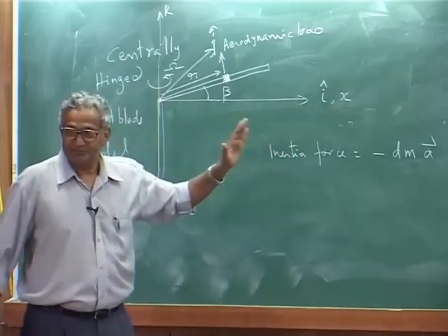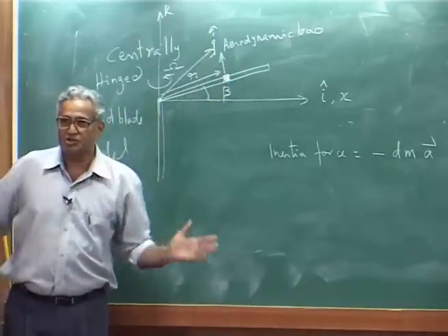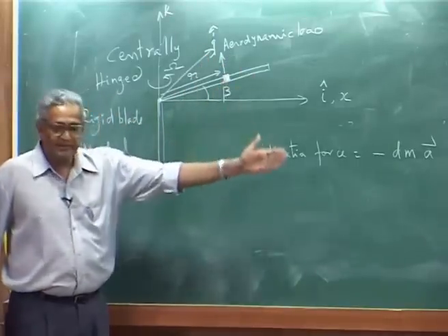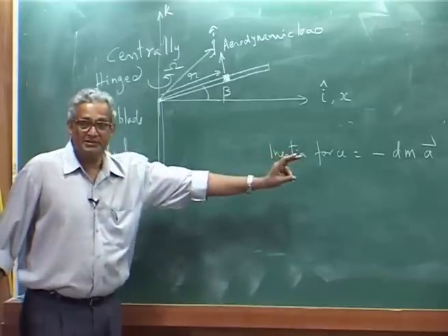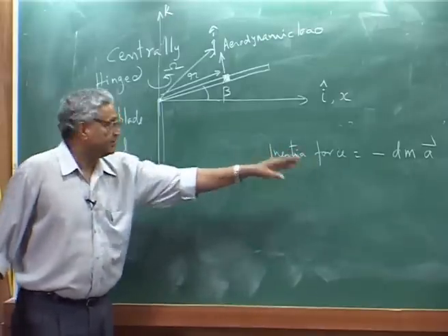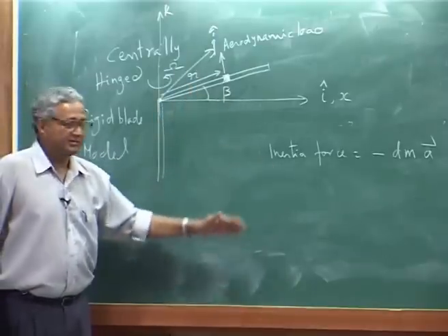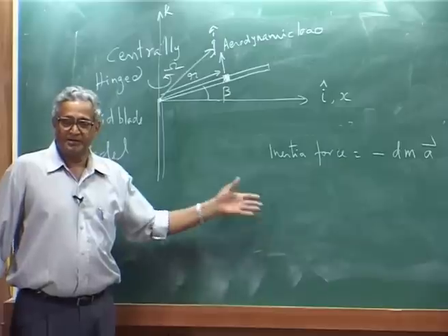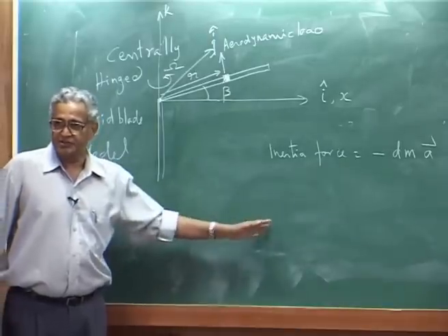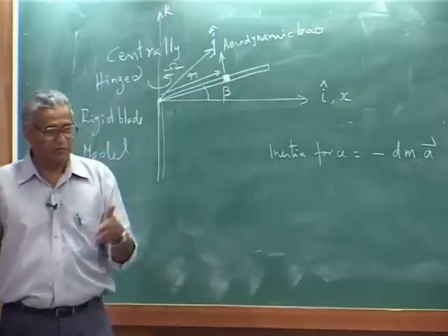But normally, if you have a very complicated motion, we write the complete acceleration expression, take the inertia force, and then take the moment. Then you add the external moment and the inertia moment. If you don't have a spring, it is zero. If you have a spring, add the load due to the spring also.